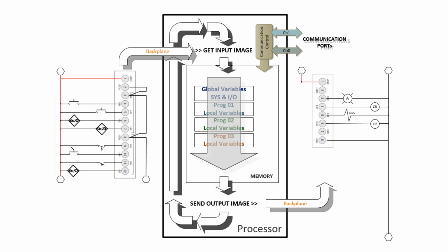And remember that a variable is a pointer that's defined as a certain data type that points to an actual literal numerical memory location in a memory array. You'll never know the actual numerical location. You'll create a variable with a data type, define it as a data type, like a counter, timer, Boolean, etc. And when you download, it's compiled and it converts all the stuff that you have, we'll say English, Spanish, whatever language you use, into actual numerical memory locations. You'll never see those, but they're there.